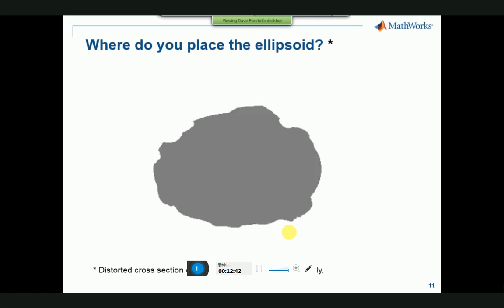These are called datums. Now, if you'll accept my very distorted cross-section of the Earth, or a cookie that's been nibbled on, we could find a place to tie a datum over here. Say, define this ellipsoid, initial position right about here, and orientation along this path. And that might be great for this location on this side of my chewed cookie or distorted cross-section of the Earth. And so that would be a great datum for us to use here. But on this other side, it's atrocious.